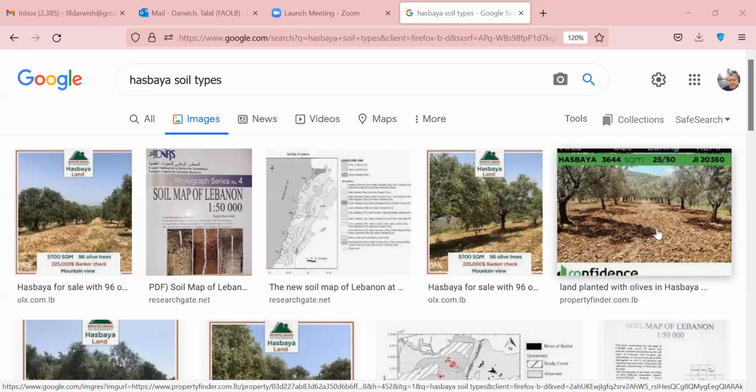Here we can dig a soil profile, and we make sure that we dig it with the face of the wall, which is going to be described like Dr. Muhammad showed the different layers, facing the sun at the moment we sample and describe. And we take the samples horizon-wise, from the soil surface to the bottom of the soil profile.